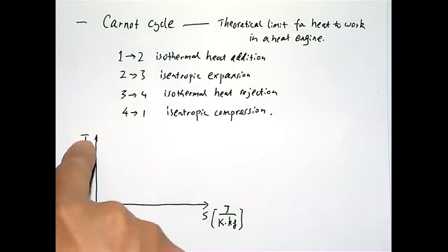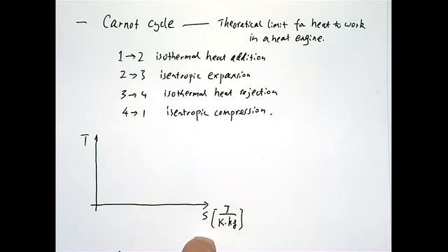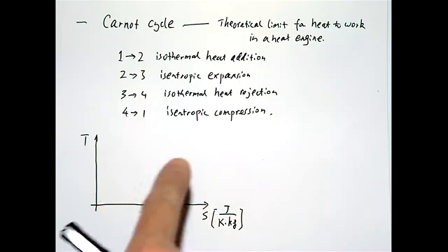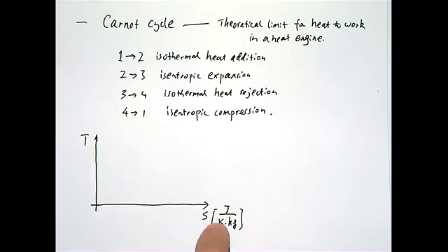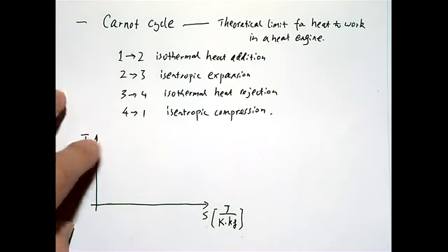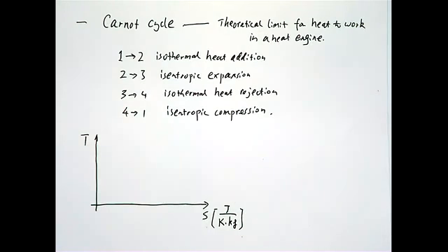You can see the temperature and the entropy are certainly independent, and temperature is intensive, and if you normalize by mass, the entropy is also an intensive property. So two independent intensive properties can describe the whole process. So that's the starting point here. So we choose the TS diagram. It can be drawn with different combinations of parameters, but we use TS here.